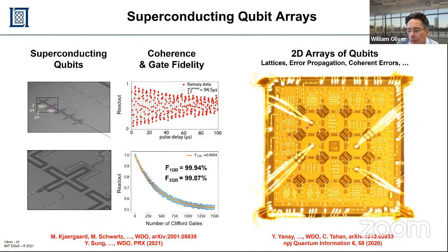And what you see here is a 4x4 array, and each one of these islands here with 2 rectangles, that's a qubit, so there's 16 here. And you see a lot of the control lines and the readout lines around the outside. And what you can see is that there's just not enough room to get additional lines into the middle, at least not in plane. So what we have to do is use wire bonds and jump over, basically break the plane. But that's not great either, because we know that this will be not impedance matched. And of course, what we really need is 3D integration.